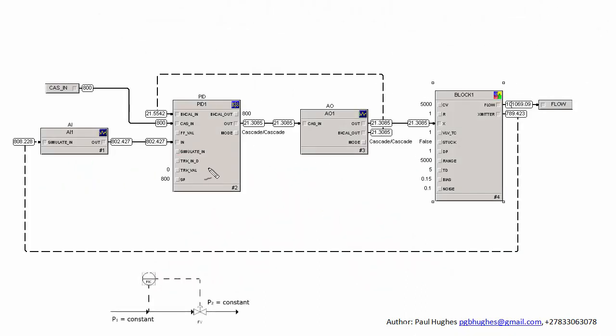So what I'm going to demonstrate here is, in a particular environment, the DeltaV or Emerson system, how you would build a PID loop. Typically you have an analog input channel, which you would configure to read in from an analog input, as I've shown in the previous videos.